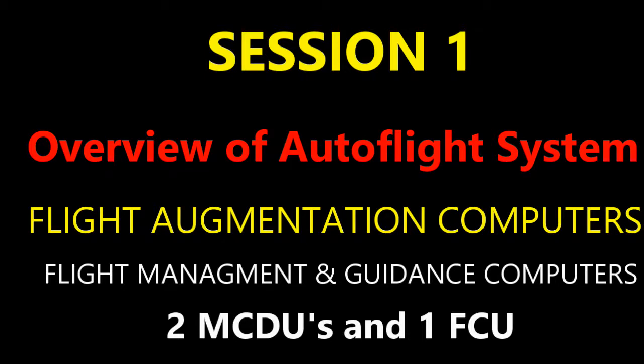Remember I said that column 4 is your approach capabilities. You've got different categories for landing, and line 1, because line 1 was for your active mode, is the text that relates to landing category. So you've got your Cat 1, Cat 2, or Cat 3. That's always going to be white. Just always check with your AMM, but I'm going to say typically white. So line 1 is landing category. Your line 2 text is going to pertain to the operational status of that particular landing category.